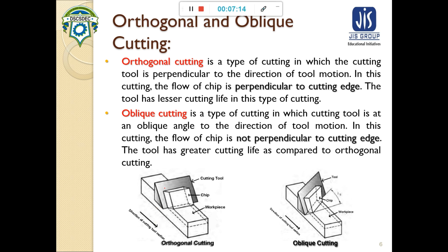When it is perpendicular, the chip will flow perpendicular to the cutting edge, above the rake surface. This type of orthogonal cutting is known as two-dimensional cutting.